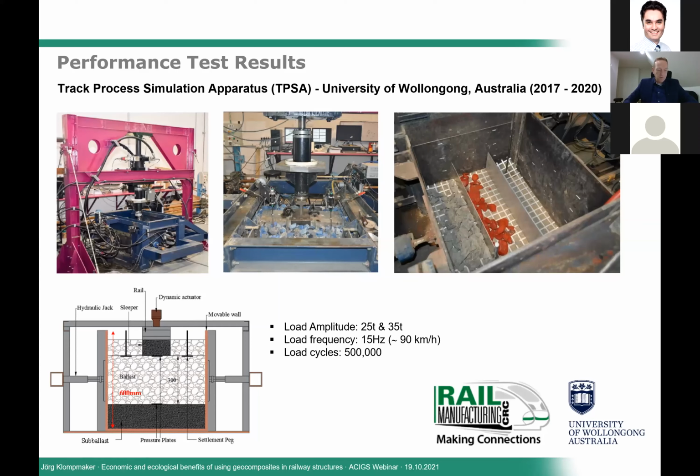The amplitude of the loading is between 25 tons and 30 tons at a frequency of 15 Hertz, which is equivalent to approximately 90 kilometers per hour. In total, 500,000 load cycles were applied.